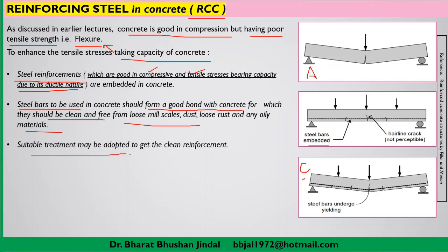Suitable treatment may be adopted to get the reinforcement clean. That means you can use any type of sandpaper, and if any scales or any dust is seen on the steel, you can clean the reinforcement using the sandpaper before embedding it in the concrete.